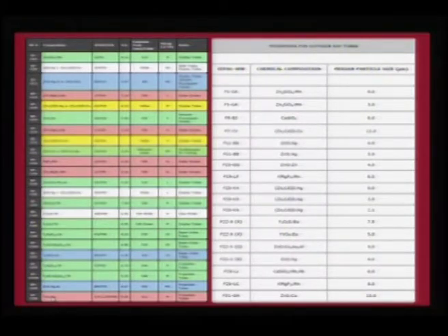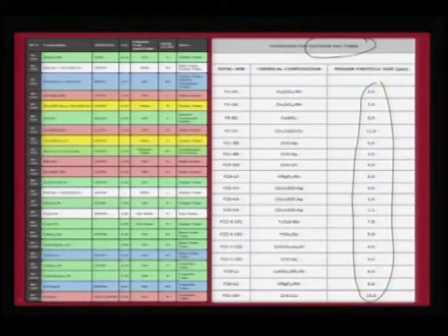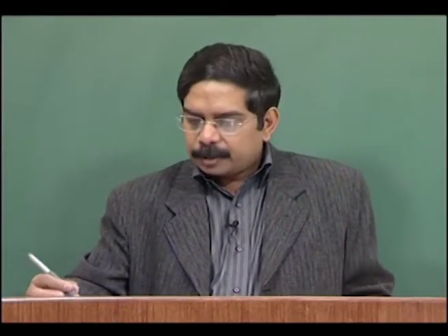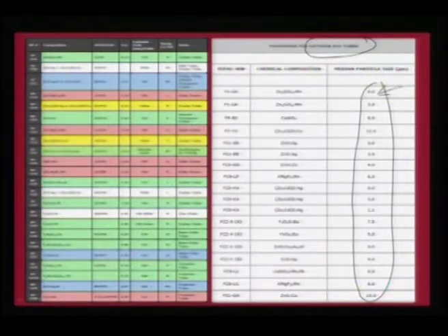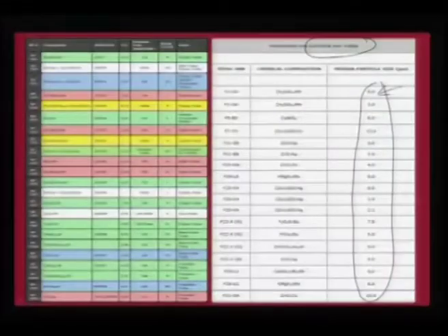And in this view graph, it may not be very easy for you to read through all the numbers, but I am just picking out this column for discussion in this slide. As you would see here, these are all the candidates used over the years for cathode ray tubes, and those who are engineering these CRT monitors are usually very sensitive to the choice of the particle size of these phosphors. So, if we are going to make them using a chemical route or by some other route, it is not just important to get the emission peak which is desired.